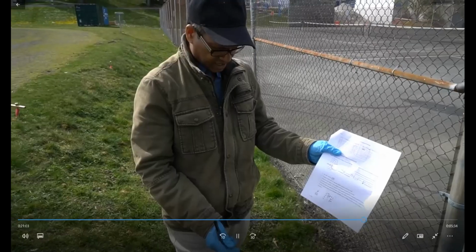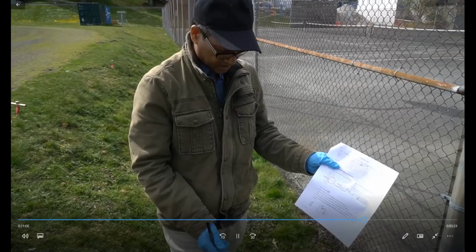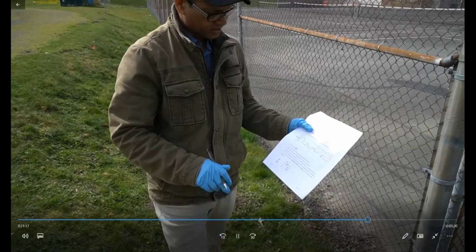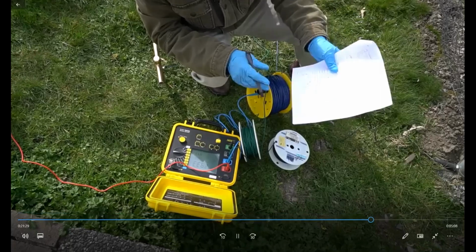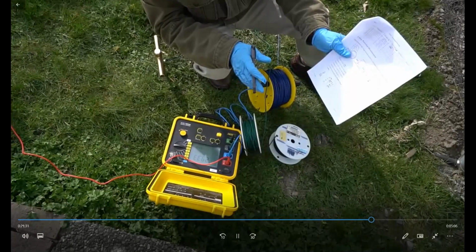Now the next and last part is step potential. So we'll set up our meter and all those probes together, and I'll discuss how we will be collecting data, and we'll show the data that will be collected. For step potential, these middle 2 probes we have to keep 1 meter away from each other. These 2 probes will represent 2 legs. Okay, so that's what we'll be doing.